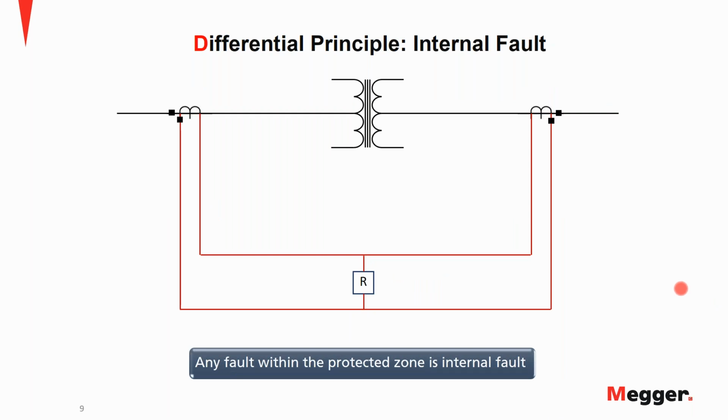When we get to an internal fault, inside the protected zone of the relay here, our currents are flowing almost in the same direction, but they actually turn around and come back to feed this fault, right? So when we run the currents on the secondary side, they change direction, and then this current adds up at the summation point that you're going to see here at these nodes. And once the differential current adds up, it goes across the relay, and then the relay issues a trip, right?